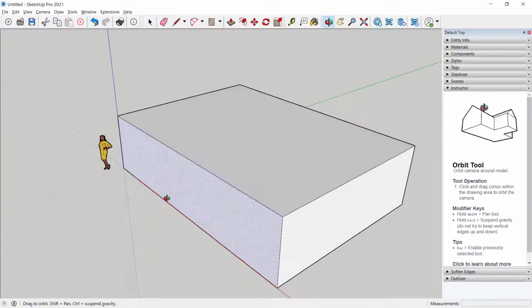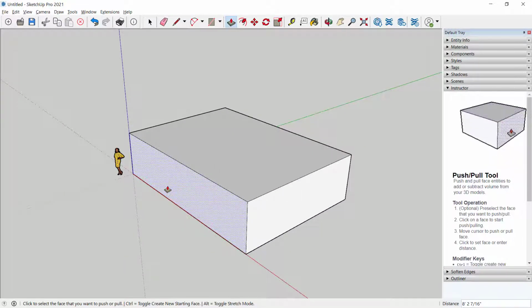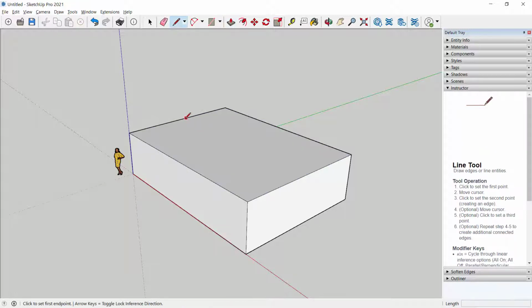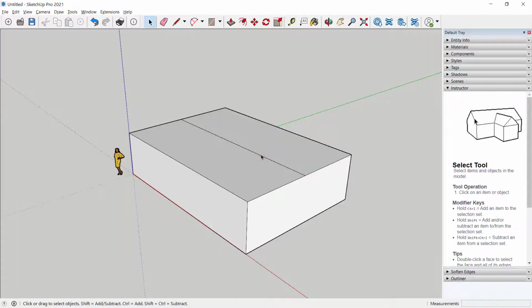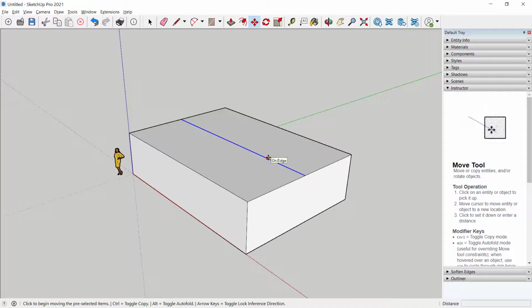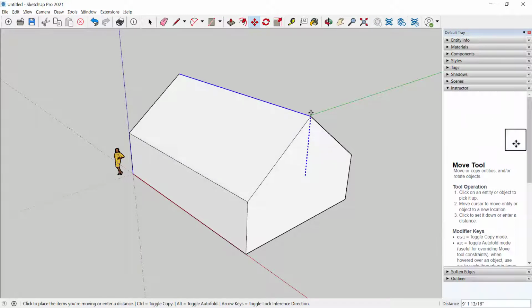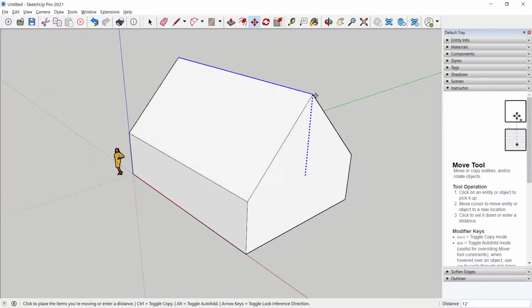And now, how am I going to make that roof? Well, it's pretty straightforward. SketchUp has that sticky geometry we mentioned. So if I draw a line, and I'm going to draw it from the midpoint to the midpoint, because if you think of that building and its roof plan, the roof is right in the middle, right? It's the ridge line. I can now select the ridge line, tap the move command. I'll even tap the up arrow so that the object will only move up. And now I can drag the roof up.